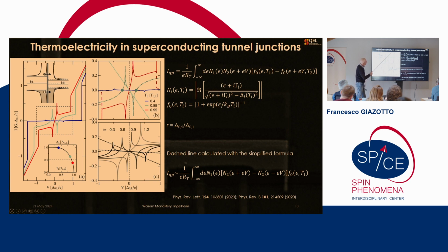So we could think that if we close the circuit over a load resistor, whose characteristic is given by this straight line, when we intersect the curves, for a given load this gives us a solution in terms of the proper thermovoltage and thermocurrent that will be set in our circuit. So we start to produce like an engine. The current can circulate in one direction or the other direction. This is why it's very nice, because the system is fully bipolar.